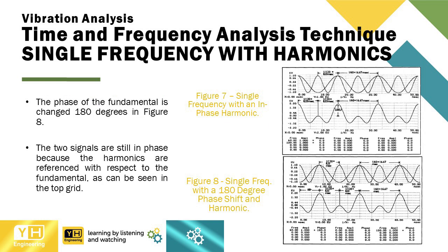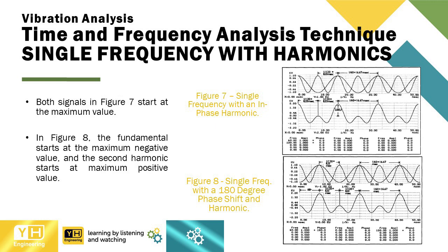The phase of the fundamental is changed 180 degrees in Figure 8. The two signals are still in phase because the harmonics are referenced with respect to the fundamental, as can be seen in the top grid. Both signals in Figure 7 start at the maximum value. In Figure 8, the fundamental starts at the maximum negative value, and the second harmonic starts at maximum positive value.